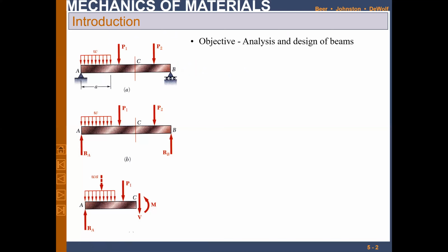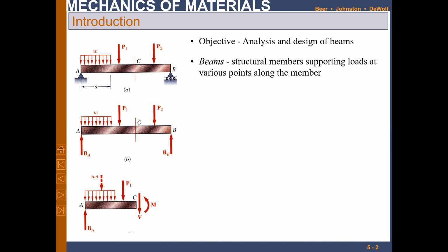These are very important parts of the design, because by using the shearing force and bending moment, you know where the maximum moments are occurring and where the maximum shearing force is occurring. So both of these will tell you which points are more vulnerable to failure, right? So these beams are obviously a very important part of the structure.